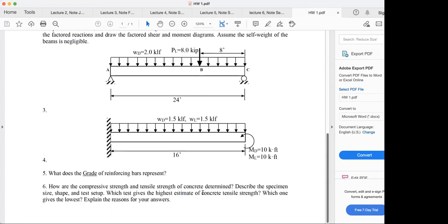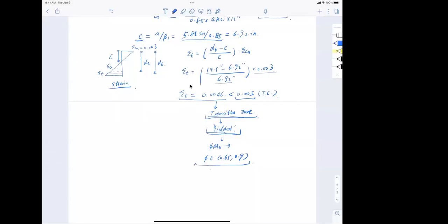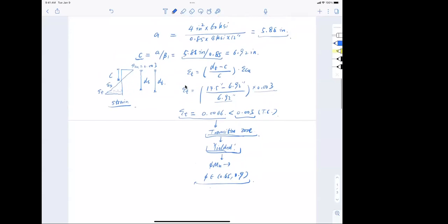Drew, you have questions as well? Yes. Okay, go ahead. I'm a little confused conceptually about when we want something to be under-reinforced. I guess in my mind, what I have right now is that whenever you're putting a force on the concrete beam, we're trying to calculate this strain factor of the steel whenever the concrete is going to bust, right? Yeah, well, you think this way: no matter what you do, the concrete has to crush at the end of it.